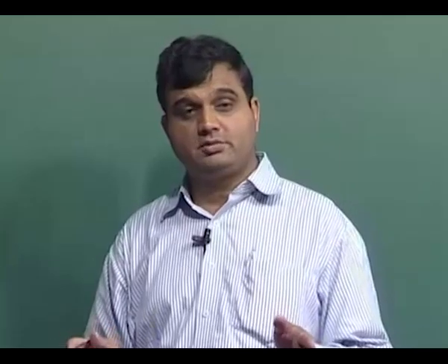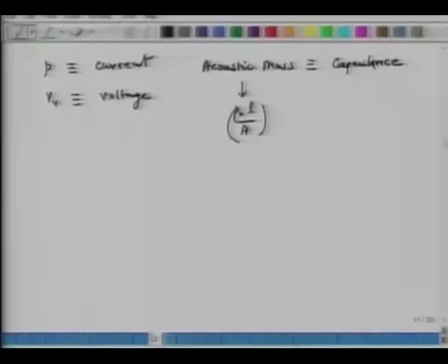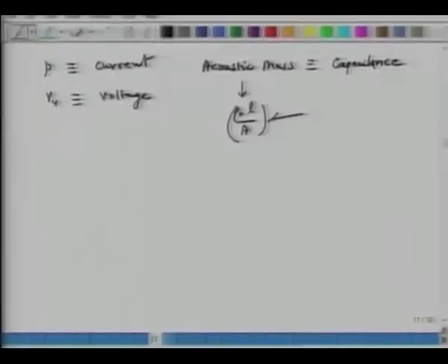If I have a short tube and I am using mobility equivalence, then the total amount of air behaves like a mass, but it's an acoustic mass, so it's not the physical mass, and the value of that acoustic mass is rho naught L over A.